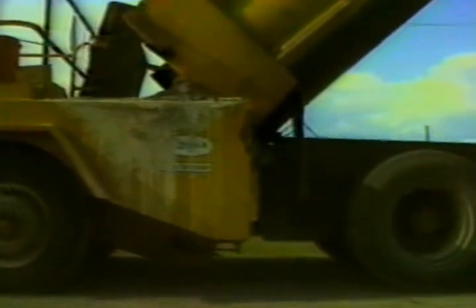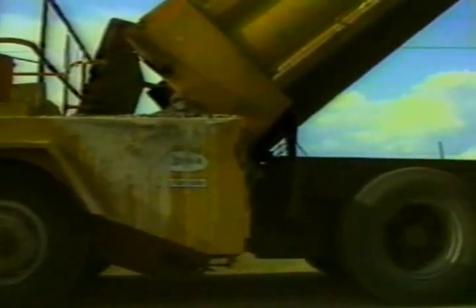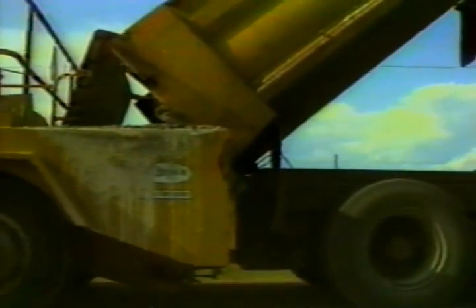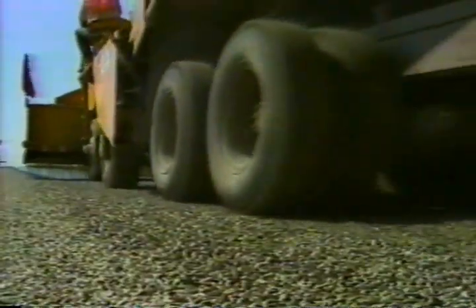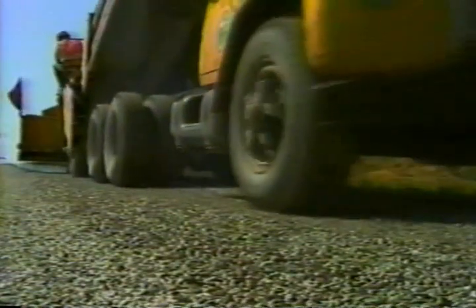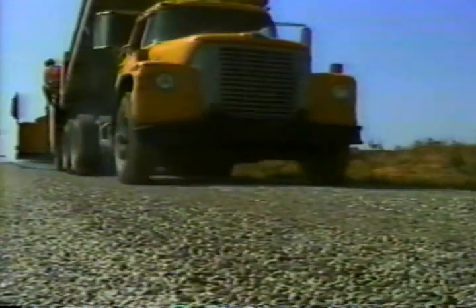Disengagement can also occur when the machines are in motion, by raising the truck bed too high or running over chip piles. In either case, if the rear of the truck is lifted high enough to clear the chipper hitch, the load ends up on the roadway.